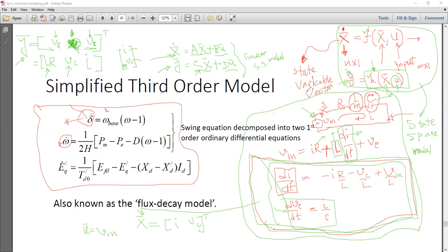Or any device which can capture the dynamics, you can measure it. It's easier compared to thinking about how I'm going to get di over dt. No need to think about it. As I said, it is up to the designer. So you choose your I as your output variable if required, and you take any measuring device and you get the I, and then you calculate di over dt if required.